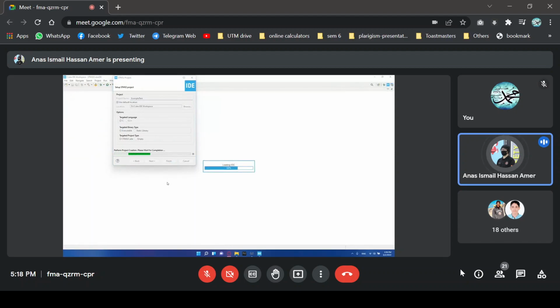This is the same as we did yesterday. We'll use the same peripherals also. We're going to use the GPIO for the sensor input. We'll use the timer and the interrupt for counting the seconds between the two sensors. And then we'll use the UART to print the speed.